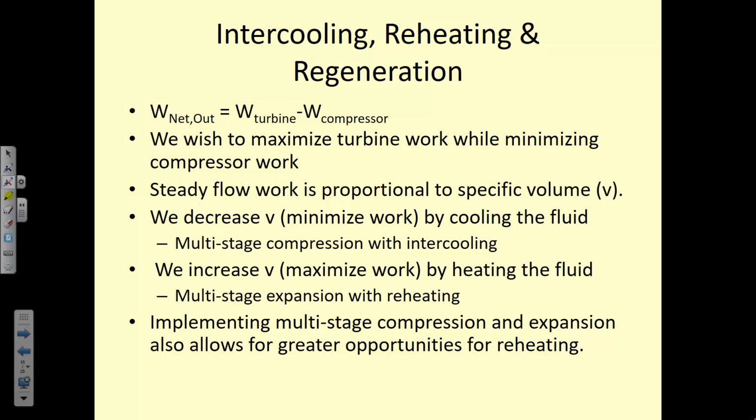It has no effect on back work ratio because the turbine is still required to power the compressor. The compressor hasn't changed, the turbine hasn't changed. We've only changed the inlet temperature of the turbine using some of the exhaust from the turbine exhaust to preheat it before it goes in. Okay, that's all we're doing.